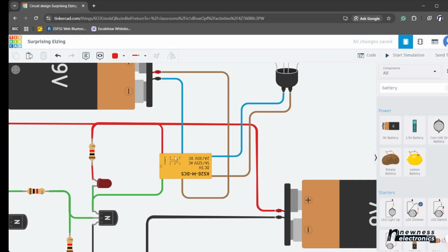When this coil is energized or powered on, it draws in some current. When power goes off, it immediately generates a reverse current that is sometimes many times higher than the supply voltage. When that reverse current happens, it wants to flow back into this transistor. Sometimes it exceeds the rating of the transistor, and therefore it can blow up your transistor.